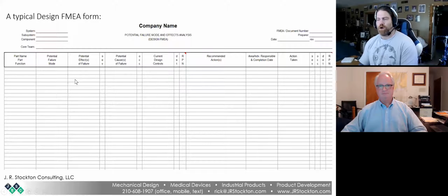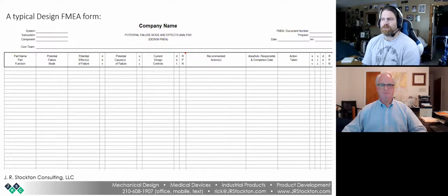But keep in mind, all these things were in the annexes at the end and in the guidance, and they're not necessarily wrong. They're just not what they meant. What they meant is you shouldn't be using detectability to reduce your design risks or your RPN scores when it's not something that can be done prior to delivery to the customer. And you can interpret that a lot of different ways. Some companies keep the detection column out of their design FMEAs because of this. Some companies include it here, which is the more classic way to do this.